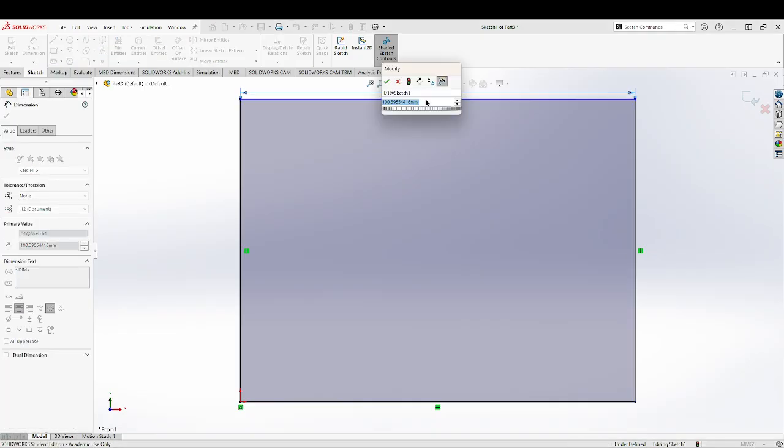So in order to use the global variables, I'm just going to enter equal. Global variables, I know that the entire length is 12. So I'm going to start with the very first one that they give us, which is B, divided by 2, plus, open quotation marks, A, close it up.